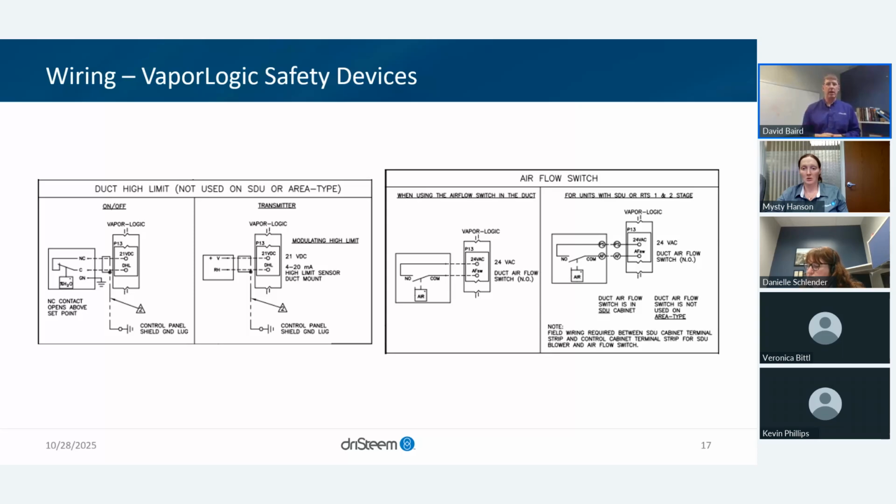I want to achieve that target, and the modulating high limit is used to throttle the output if it's going to get near saturation or whatever that high limit set point is. So there's two different settings. One is, okay, what is the condition I'm trying to achieve, 40% relative humidity, and then there's a separate setting for what is the maximum amount of relative humidity I want in the ductwork, as an example. Whether that's done at the high limit humidistat, which is a dial, or I put it in the controller, don't allow me to go above 80% relative humidity. So that's different spots, different settings to be able to use for it.